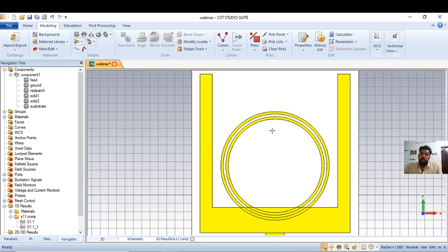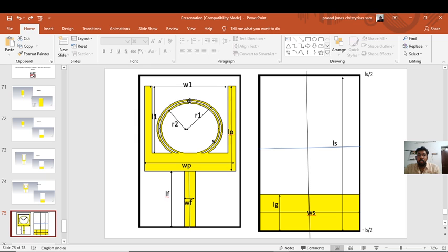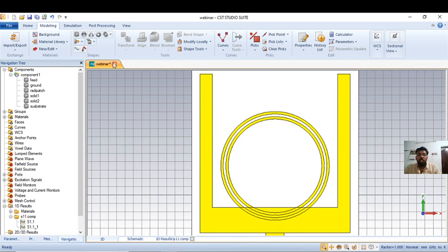You can view that there are two rings available here, and then you have to have a split like this. So click on brick, escape. That is a split here, a co-direction split. So click on brick, escape.